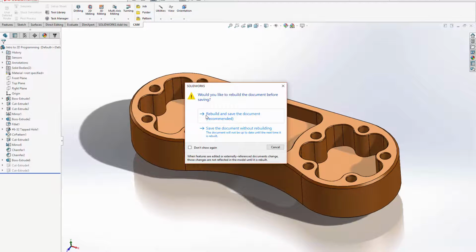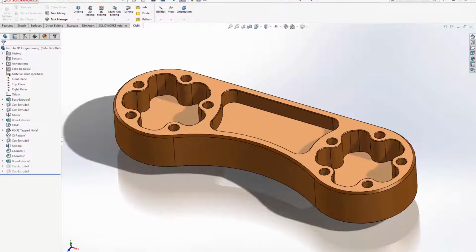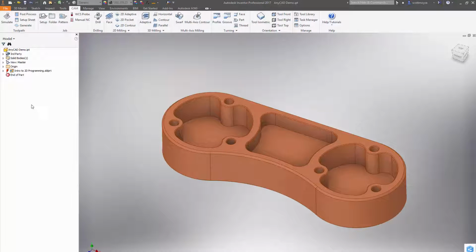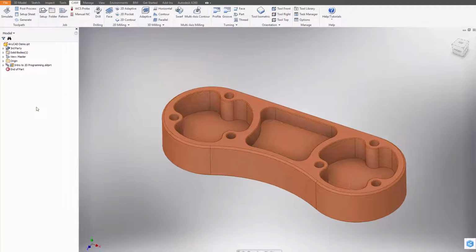So we'll hit save on here. Everything's updated. Come back into Inventor and we can see that there's a lightning bolt in here now, and when we come back into this browser we can see that it's pending a change. Now if you want to, you can also just right click on this and go suppress link. Alright, so it's never going to try and update. It's as if you imported it in the traditional manner, and so there's no live link back to the original file.